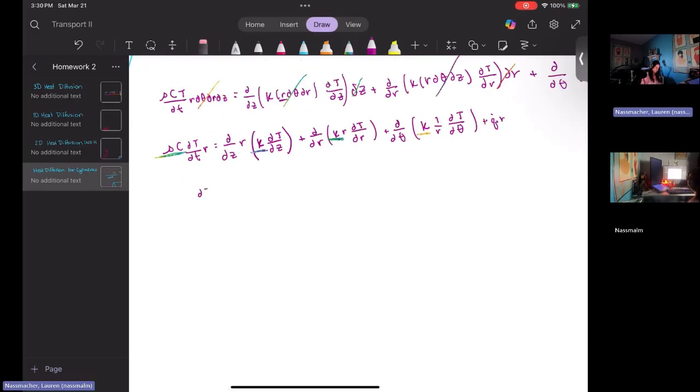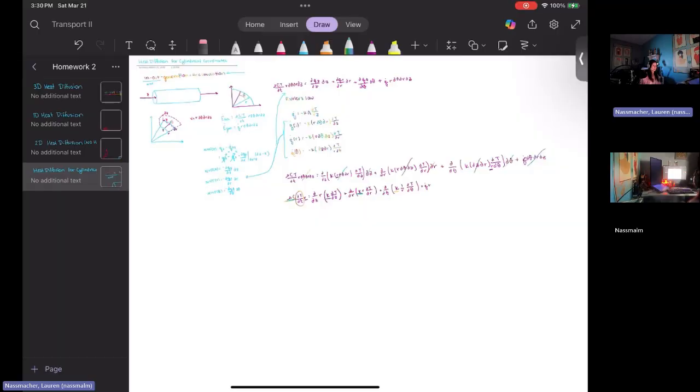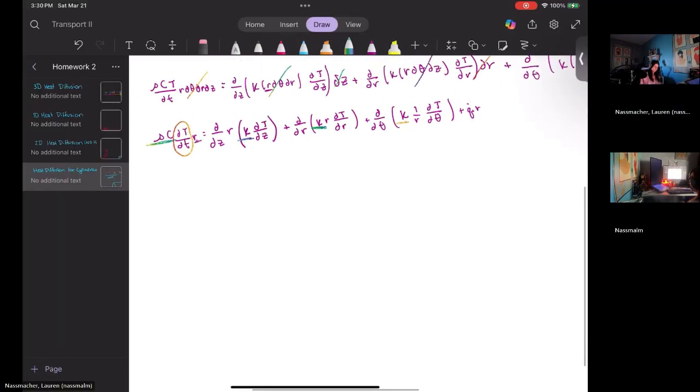So we also want to divide this radius over. That's a very important thing to do because we want to single out this part of the expression, our change in temperature over our change in time, because that will let us know the heat diffusion equation for a cylinder. So we have change in temperature over our change in time, and that's going to be equivalent to our thermal diffusivity multiplied by our change in the z direction.